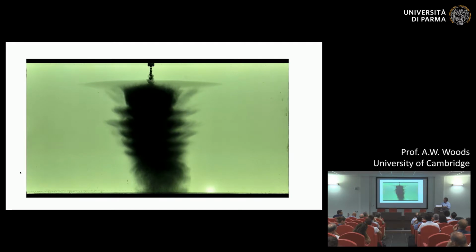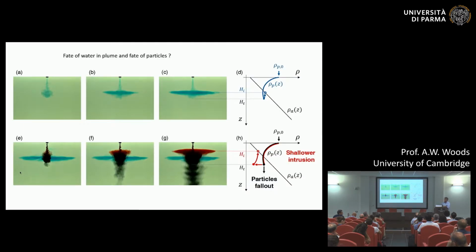And so to understand some of the basic aspects of this flow, if we consider the salt plume again, so we have our stratified water column with the fluid going from being fresh to being salty, and we release some salty water, it entrains and mixes, and it forms a neutral height at some intermediate level. Okay, and so if we look at density with depth, what you see is the density of the flow coming in is very high. As it sinks and entrains this ambient fluid, the density decreases. Eventually it reaches the ambient, it overshoots a little bit, but it then intrudes at this neutral height.